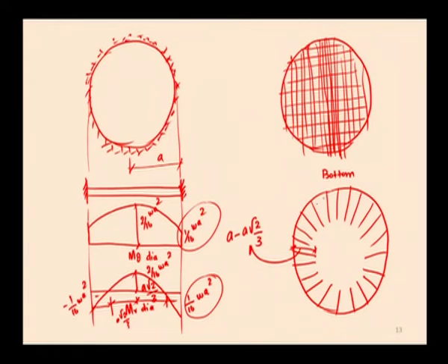And in order to keep this reinforcement in the proper position and also to satisfy the circumferential moment of 1 by 16 W A squared, there is circumferential reinforcement which has to be provided in the circumferential direction. This is the reinforcement which is not only to resist this circumferential moment, but also to keep the top radial moment reinforcement in the proper position and also to avoid the sliding of reinforcement.